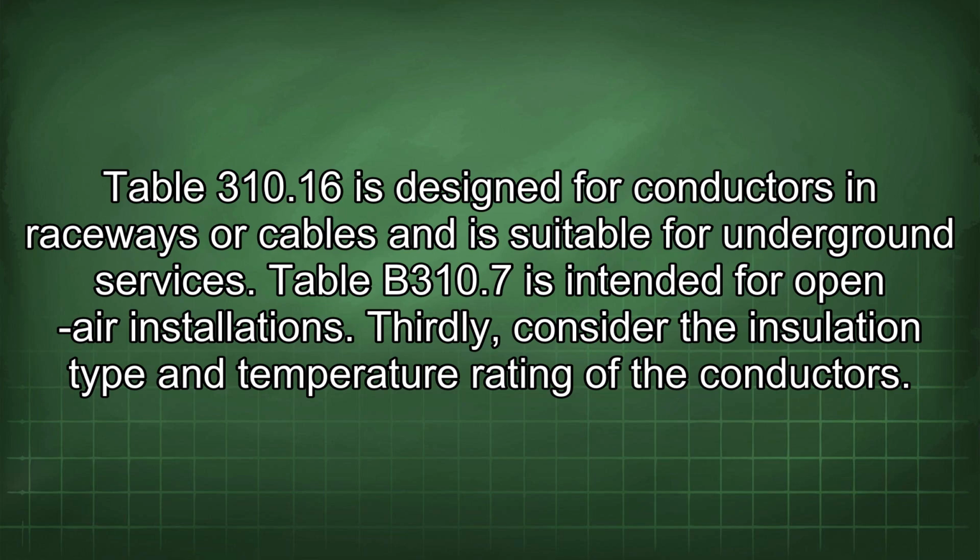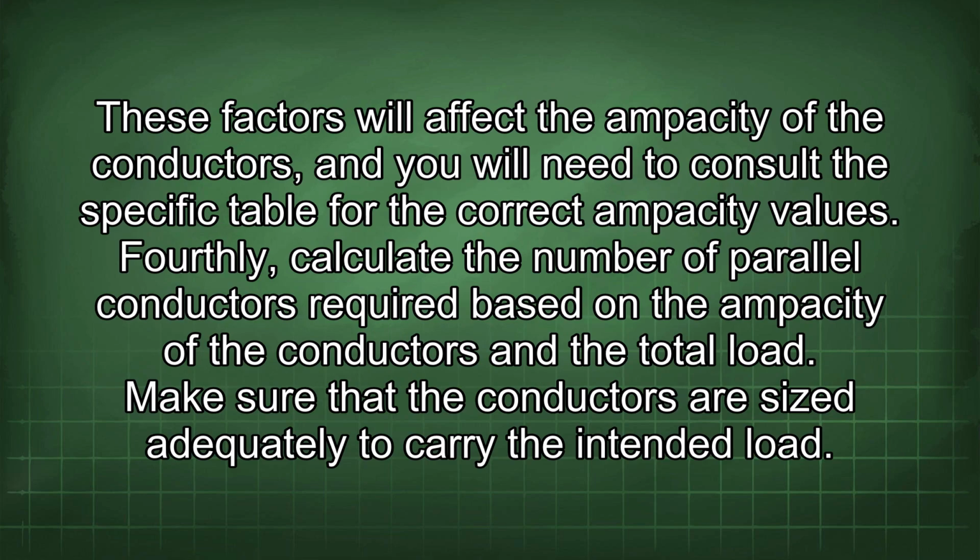Thirdly, consider the insulation type and temperature rating of the conductors. These factors will affect the ampacity of the conductors, and you will need to consult the specific table for the correct ampacity values. Fourthly, calculate the number of parallel conductors required based on the ampacity of the conductors and the total load. Make sure that the conductors are sized adequately to carry the intended load.